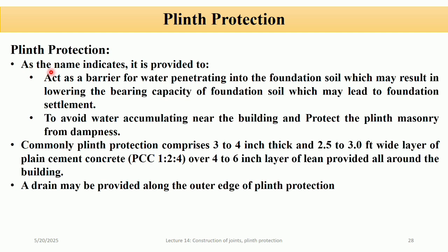Plinth protection. Plinth protection is a protective layer provided around the plinth, the base part of a building between the foundation and the ground floor level. We provide the plinth protection to prevent water penetration into foundation soil. Water penetration can reduce the soil bearing capacity, leading to uneven settlement or damage to the foundation.